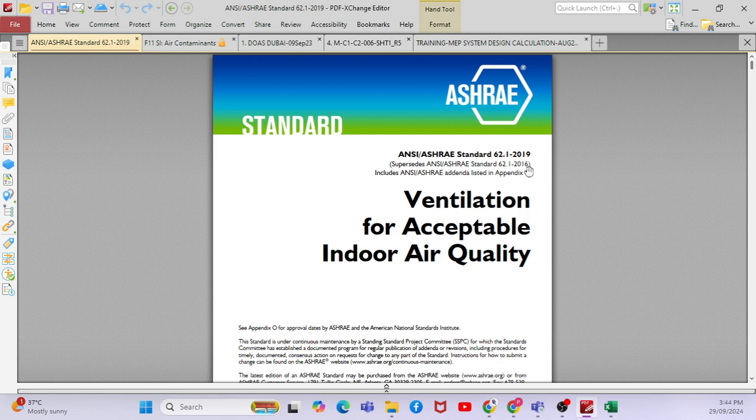You have two types of fresh air handling unit: treated and untreated. Treated fresh air means a fresh air handling unit or one-way air handling unit. Non-treated fresh air means something like an energy recovery ventilation unit. It doesn't pass through the cooling coil. It directly takes the air from outside and exchanges the energy between indoor and outdoor.